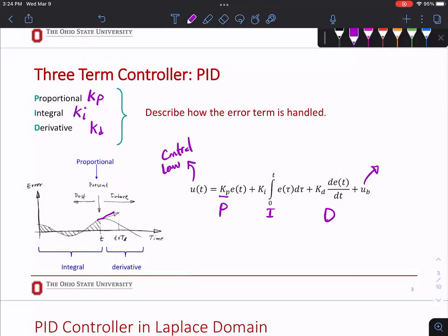I need to go from 0 to where Brad is sitting. I don't know how far that is to tell my robot to go, but I know it's at least 4 yards. 1, 2, 3, 4. That is the feed forward, right? I can measure where it is. From here, I'm going to keep measuring the error: 1.5 yards, 1 yard, 0.8 yard, whatever, and then I arrive. I'm reducing the error, right?